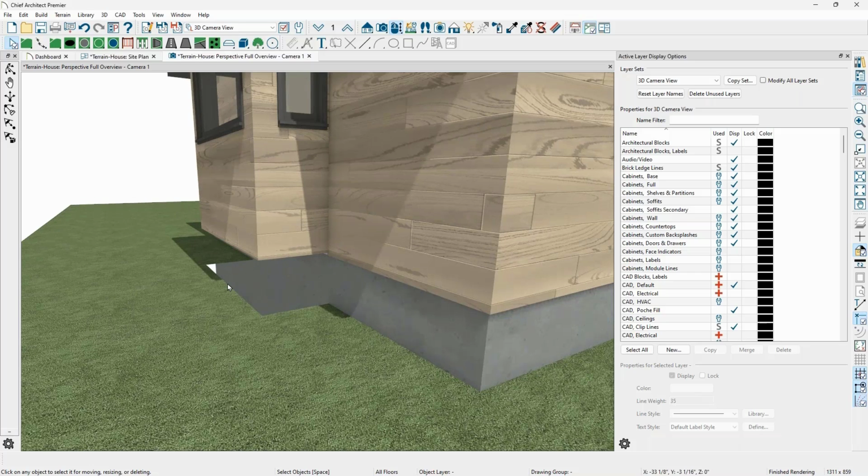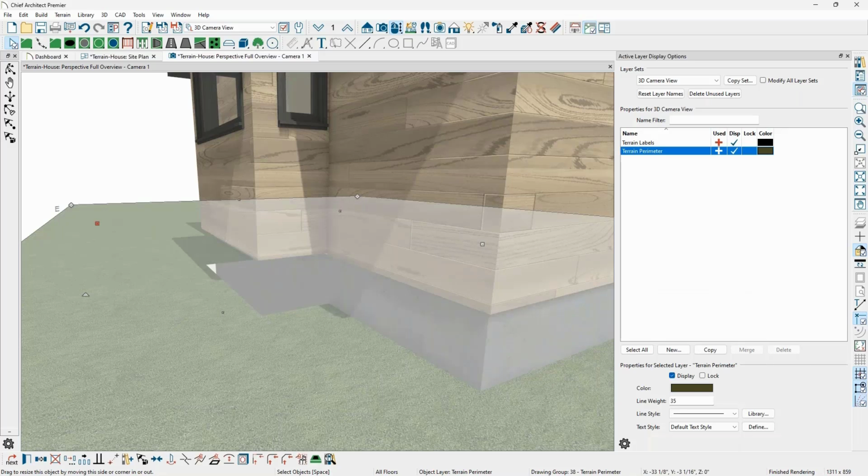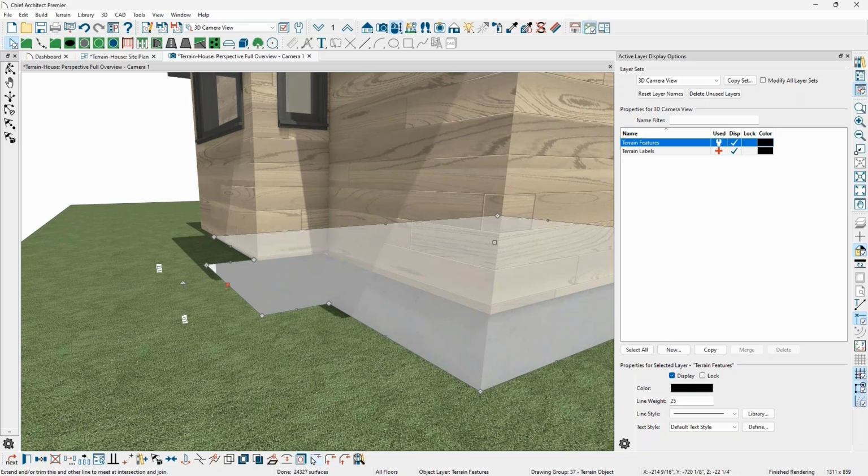You can actually click on this terrain. It was Brandon, right? Yep. You can actually click on this terrain, and I didn't see that it gave me any handles anywhere. Create a manual hole. So I'm going to click on the terrain. Okay. And then in the very bottom edit menu is this option that says make terrain holes around the building. What that's going to do is separate out the hole from the terrain. Oh, so it does give me handles. Right. So at that point, you can make it bigger, you can make it smaller. That's what I needed exactly right there.